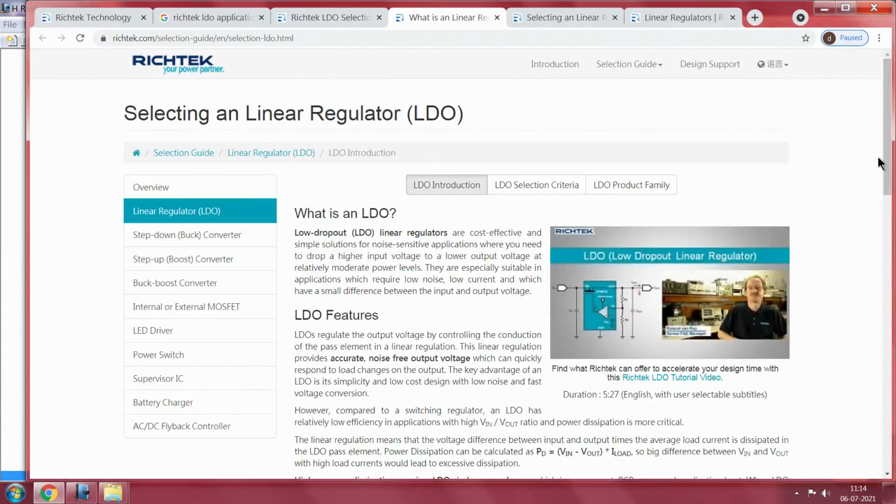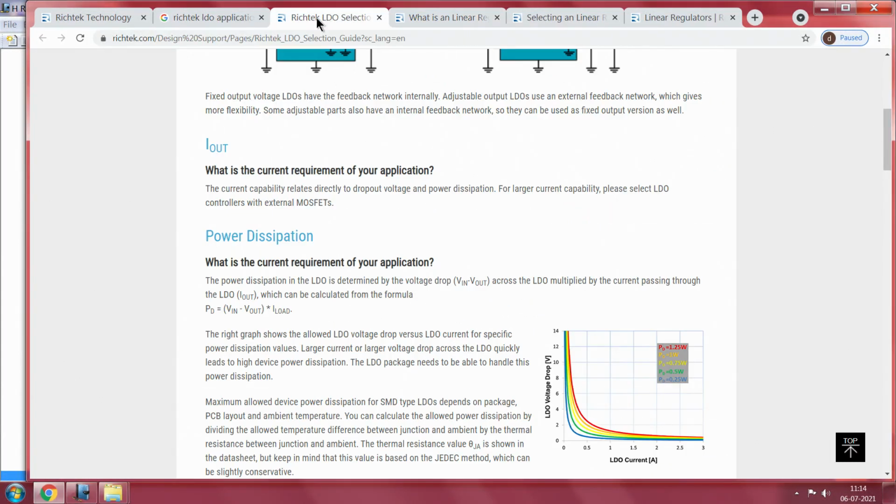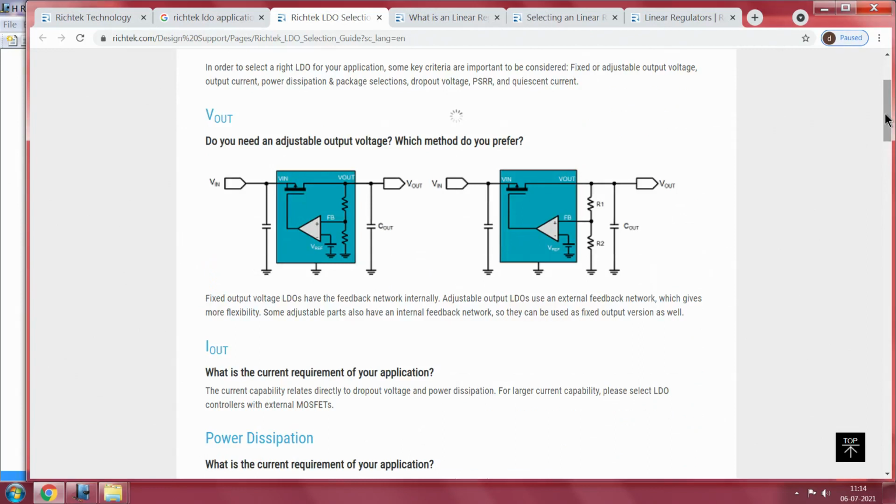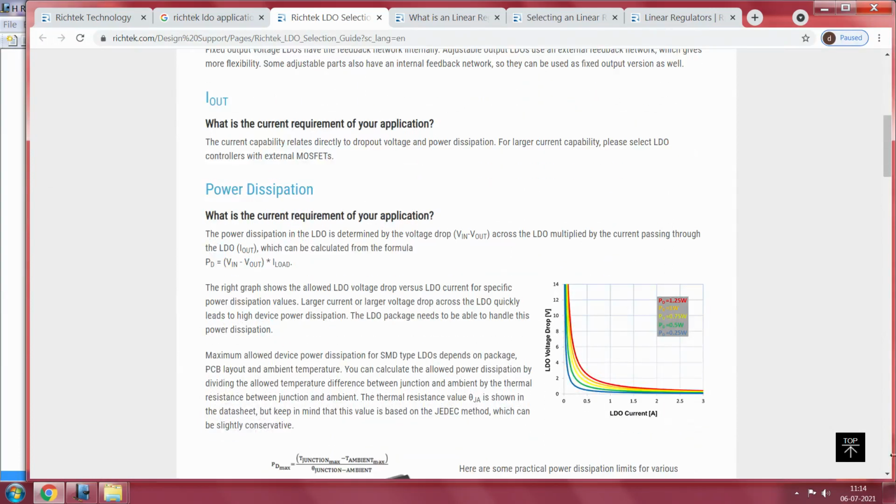Before we go on, I will show you one more note with respect to LDO. Some more few things you need to know. This is again a recap. You can see this is a P channel MOSFET. There is no additional circuitry, such as a charge pump, for generating a VGS higher than the output voltage. You do not need anything here. You have the input capacitor and the output capacitor, and this is the same thing he has shown in the picture to the right, where he shows that the sensing resistors are kept outside. So do look out for this aspect as well.